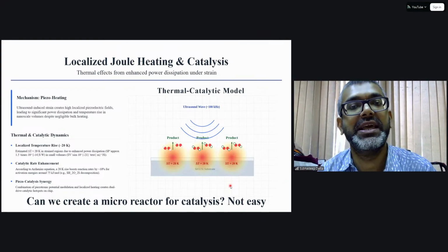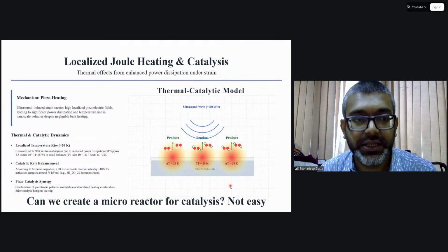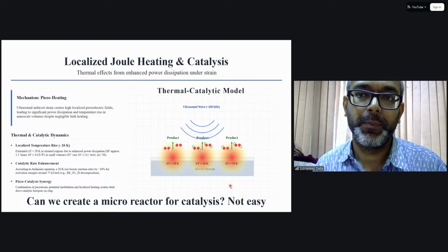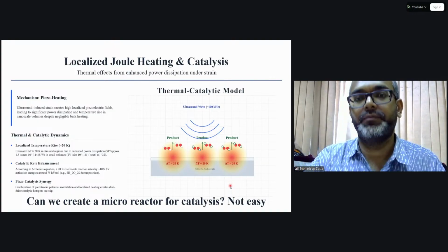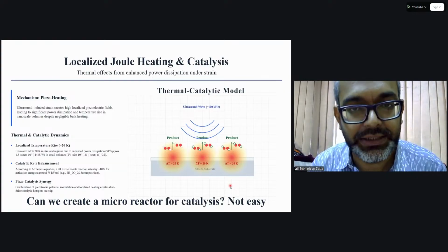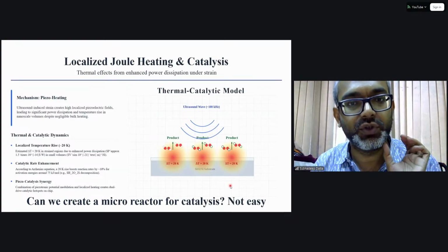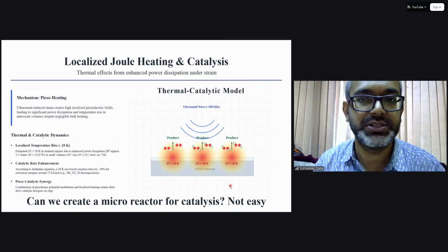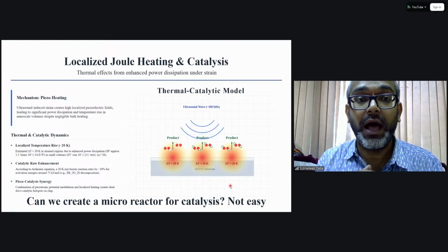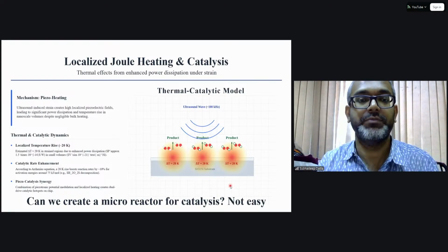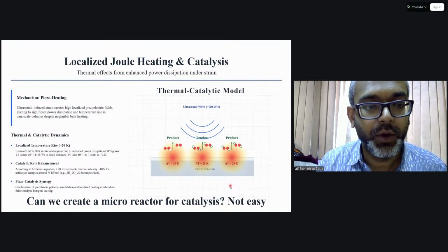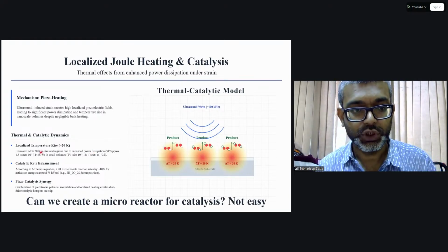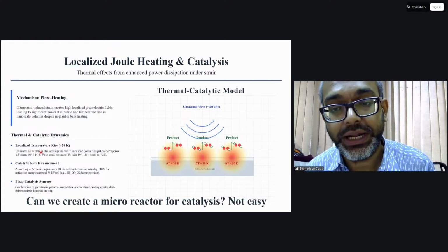I have mentioned in the application that from our circuit, we can get the idea of how, due to heating, this piezotronic current can be measured, and since we can measure this piezotronic current, there will be some localized heat because I square R, right? Now this I square R, if you calculate from the strain and the piezoelectricity, we have calculated that it is estimated as 20 Kelvin. So the temperature rise is 20 Kelvin.